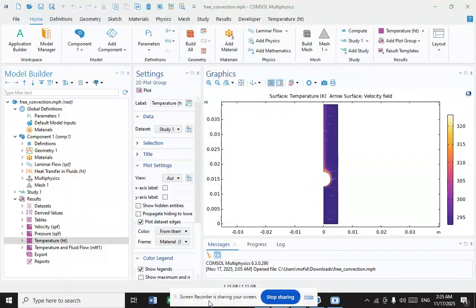As is shown by experimental data, in many cases of free convection, the main variations of the characteristics of thermal and hydrodynamic fields are concentrated in relatively narrow boundary layers near the heat transfer surface, where viscous forces are commensurable with inertial and volumetric forces. The smallness of a boundary layer thickness as compared with characteristic dimensions of bodies allows one to introduce additional simplifications into the equations of motion and heat transfer.